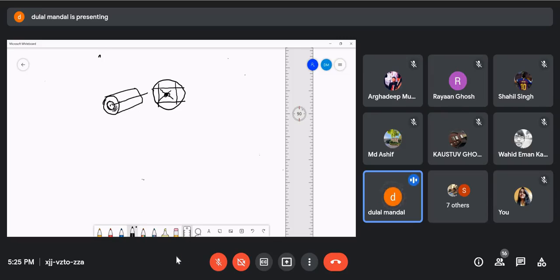Now that the small drill hole is there, you have to increase the hole diameter. We cannot use the drill now, so you have to use another tool to increase the internal diameter. That is called boring. You have to use the boring tool. So boring and drilling are different operations. Once you use the boring tool, the internal hole is created.